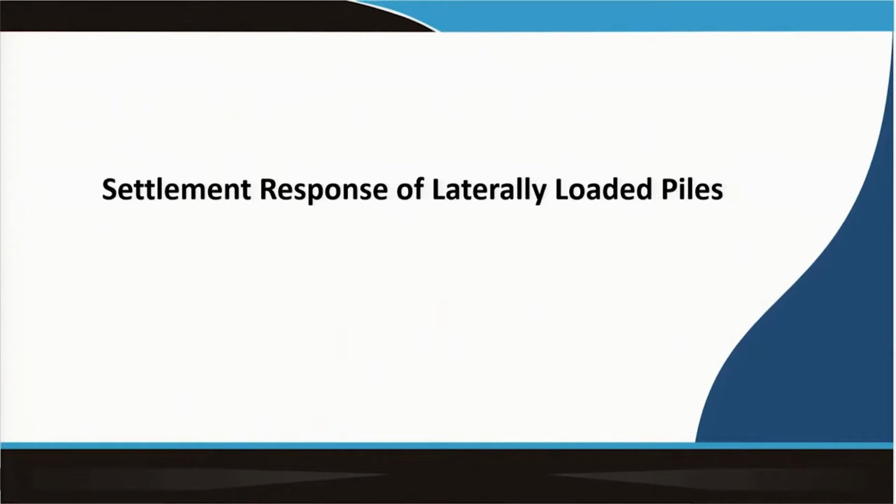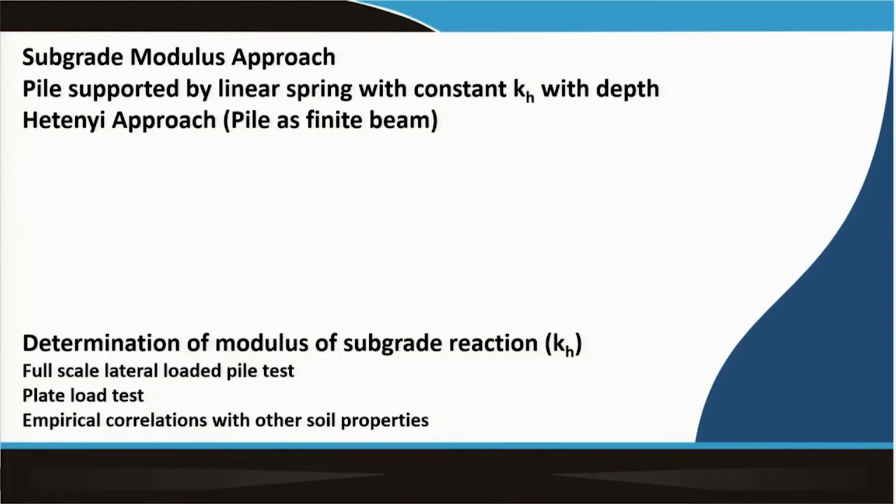For the settlement response of laterally loaded piles, the first approach that I will discuss is the subgrade modulus approach, because I have already discussed this approach during the topic on the concept of beams on elastic foundation. I discussed this concept for shallow foundations when a beam is placed over springs.